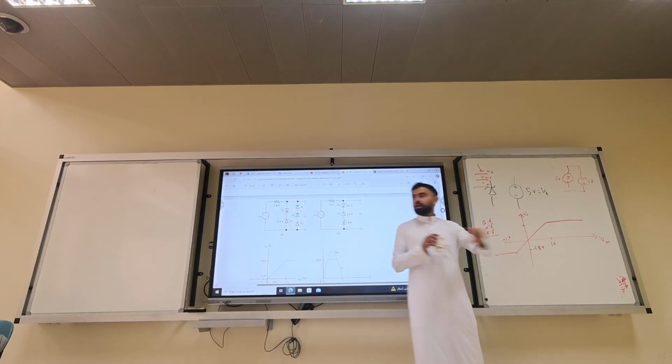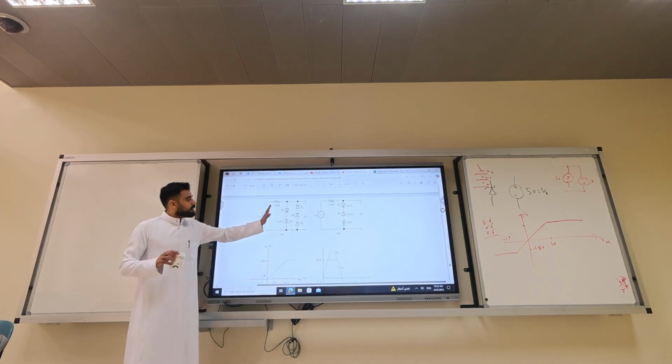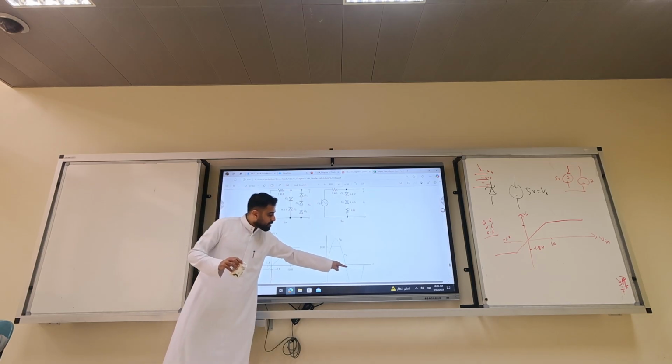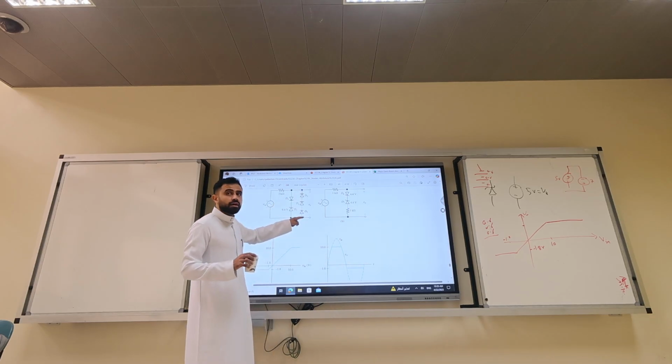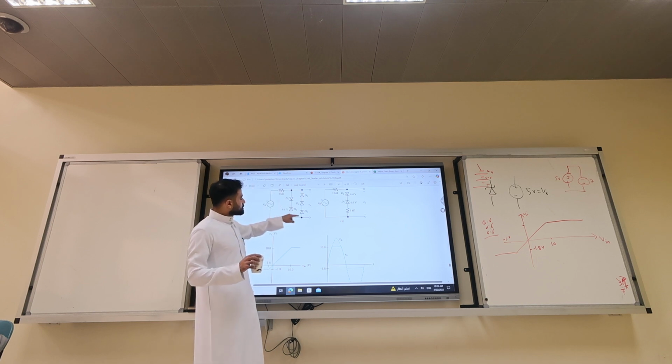Here it says 5. And then here is another diode, forward bias, will give you what? 0.6. At this period of time, at minus 1.8, these 3 are forward bias. Even though they are flipped, because there is negative voltage here, if you apply minus 5 volts, this means it is plus 5 at the negative terminal. So D5 has a higher voltage drop than D4 than D3. So the sum of all of them is what? 1.8.